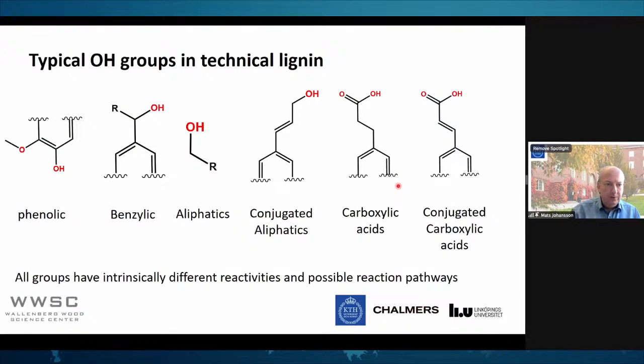In a technical lignin, you also have quite a variety of functional groups that you can use to incorporate this into thermoset systems. You've got phenolics, aliphatic alcohols, carboxylic acids, etc. And of course, you can directly use these in systems that co-react with these types of groups. Or you can use these groups to functionalize, adding a functionality into the structure so that you can have other cross-linking mechanisms. So here you also have a lot of different routes to go, so to say.